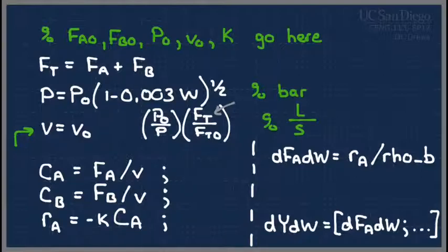The elements that we're going through here are the same elements you would need on the project. We'll also introduce later in the class, when I might have to just post a video on it, a nice trick: you can tell MATLAB when to stop solving a differential equation when one of these conditions happens inside the integration method. And we'll use that because it'll make your life easier. You won't have to try to interpret ODE solver errors, which is always fun, interpreting those errors.